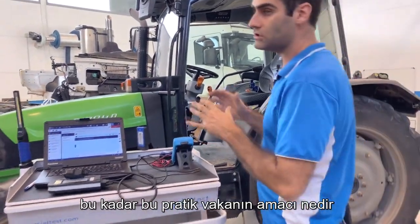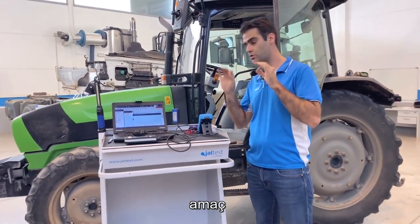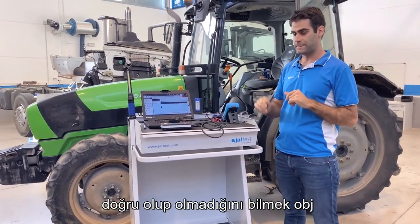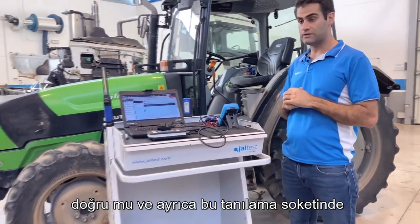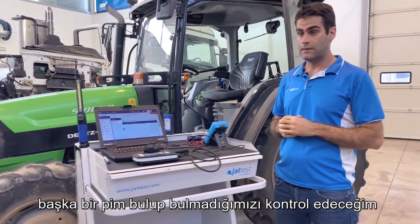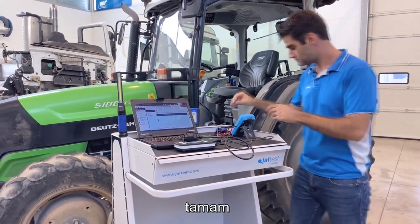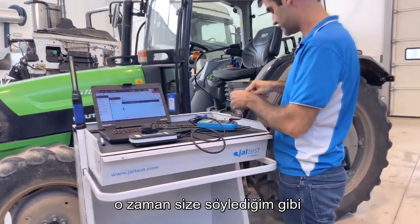So what's the goal of this practical case? The goal is to know if the voltage levels of the CAN lines are correct, if the power supply of the OBD socket is correct, and also I'm going to check if we find any other pin in this diagnostic socket. Okay, so I'm going to use, as I told you, the multimeter.